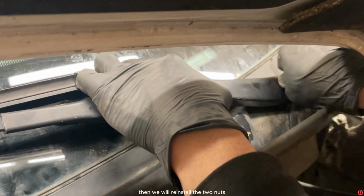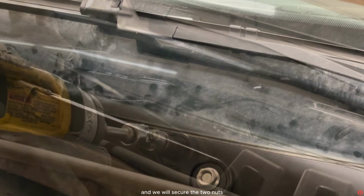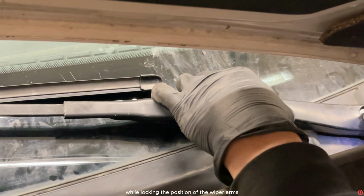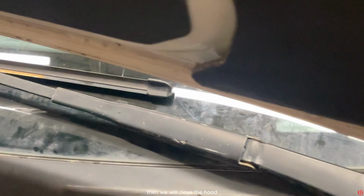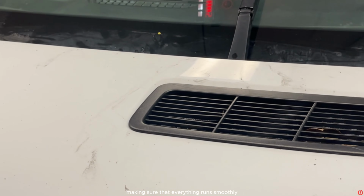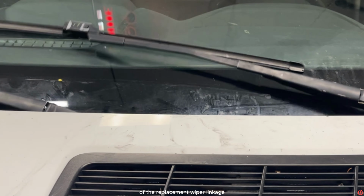Then, we will reinstall the 2 nuts that retain the 2 wiper arms in place. And we will secure the 2 nuts with a 14mm socket while locking the position of the wiper arms. Next, we will reinstall the 2 nuts cover cap on the 2 wiper arms. Then we will close the hood and make a final functional test, making sure that everything runs smoothly before completing the installation of the replacement wiper linkage.